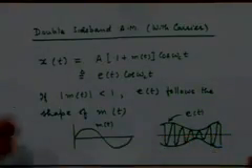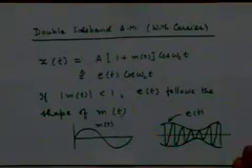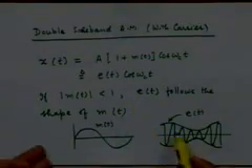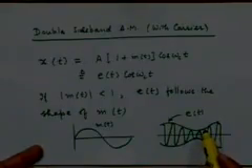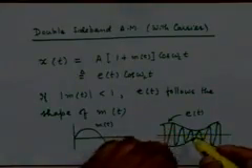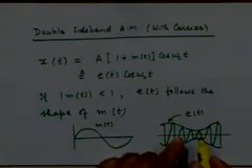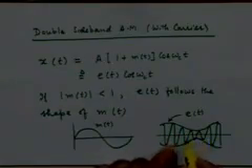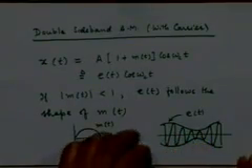For example, if the largest value of m(t) is equal to 1, the envelope will even touch the time axis. The moment it becomes more than 1, the envelope will in that region become proportional to mod of m(t), because this portion will come up. So that's what we don't want.